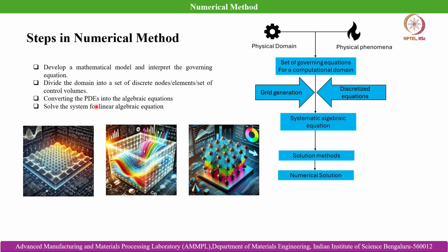We solve the system by converting the PDEs into linear algebraic equations, so that we can achieve the solution at the nodal level, and then we can estimate the distribution of a particular physical parameter, for example temperature or viscosity or the fluid velocity.